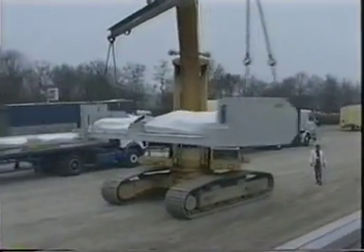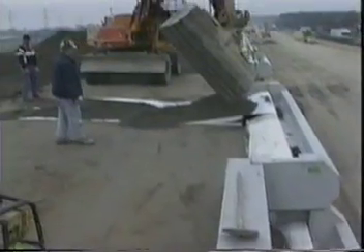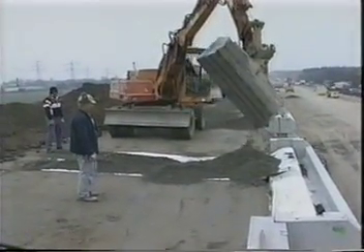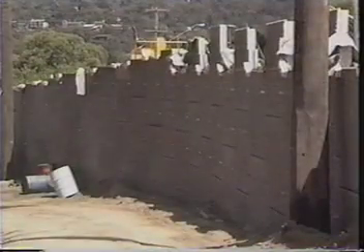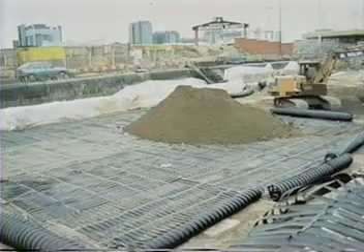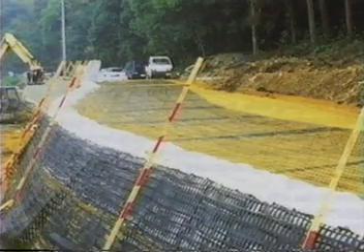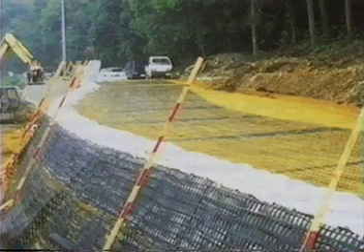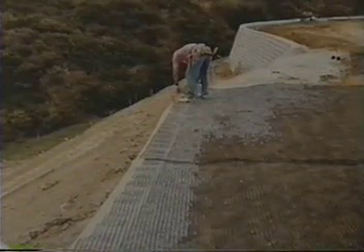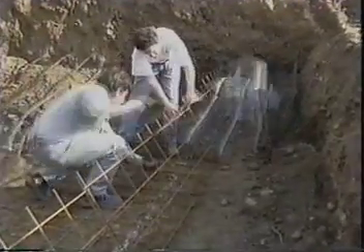Combinations of facing, reinforcement, and fill are dictated by the end use of the reinforced soil facility and the design. However, certain combinations emerge. For example, steel strip reinforcement tends to be used with partial height facing panels and non-corrosive, well-graded granular fill. Geogrids may be used with more finely graded soil because their large embedded area allows them to develop high pull-out resistance. Geogrids are often used on steep slopes constructed with segmental block facings or caged soft facings.